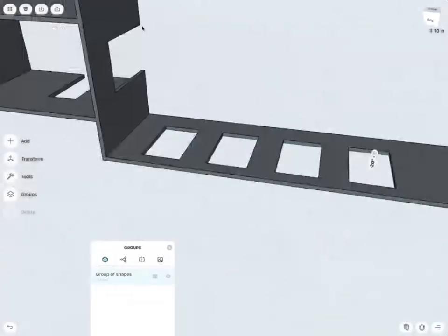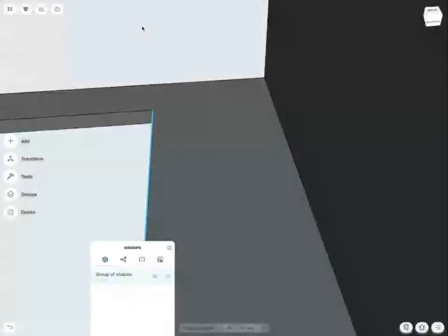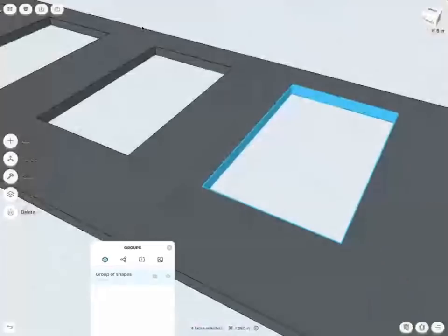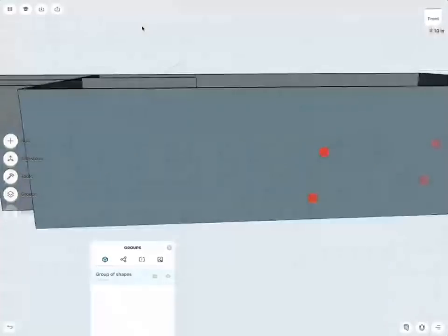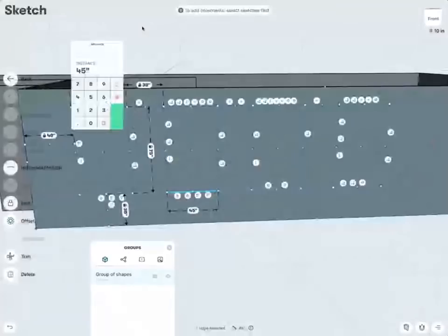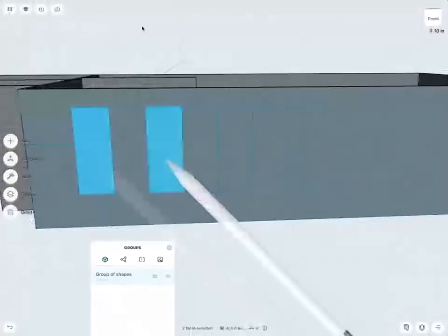The windows right now are not as easily adjustable all at once, but since we are working in Shaper with amazing direct modeling, we can select the 4 edges, and then all we do is simply delete the last command we did, and as you can see, we get back the original geometry there. And then we could go ahead and adjust the sketch. Maybe we want them to be 30 and 30 there, and then let's recut this. Very easy.